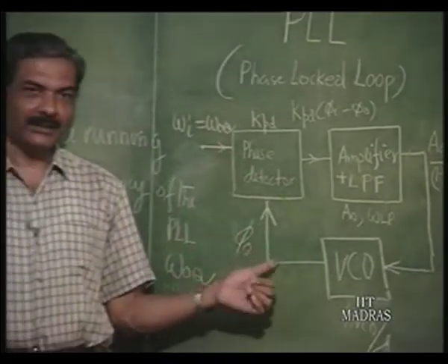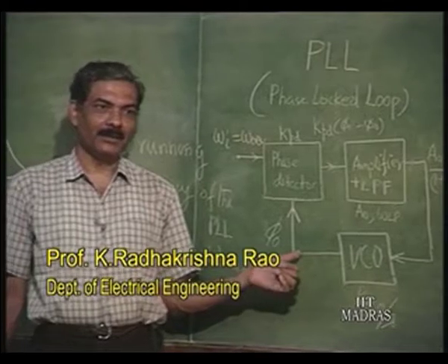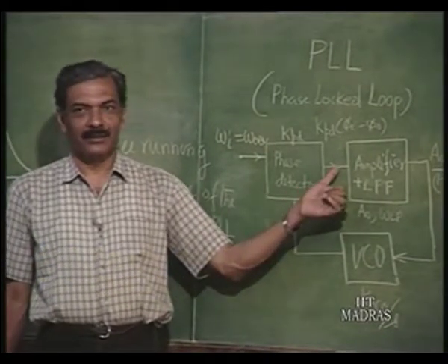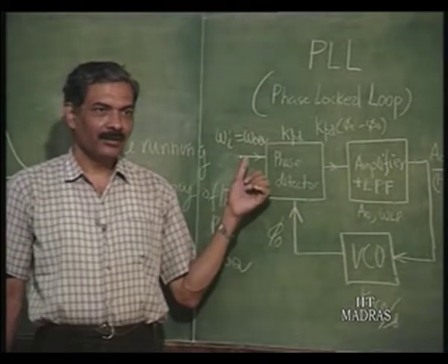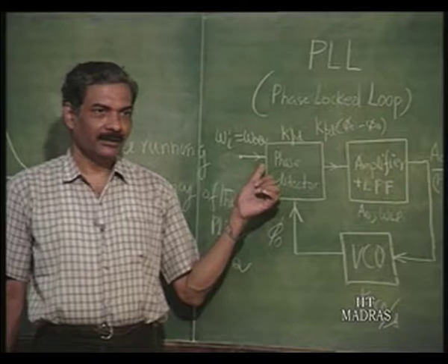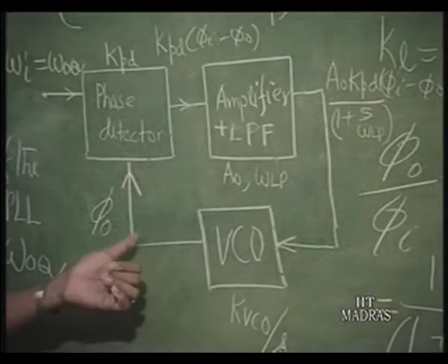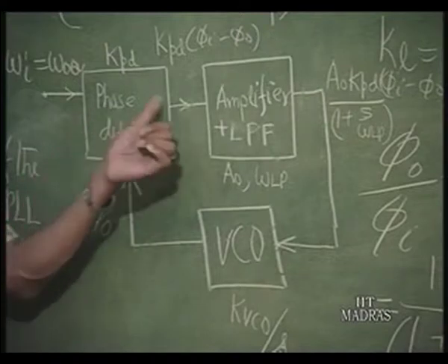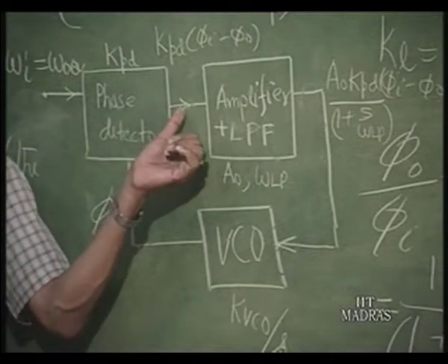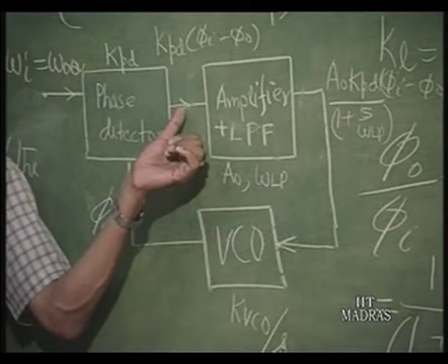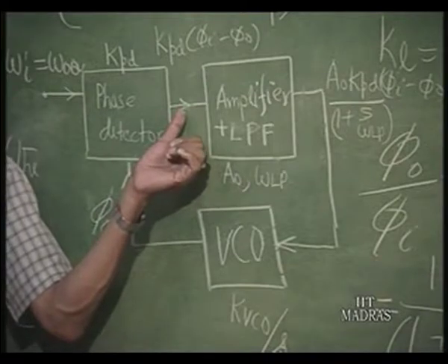That phase difference has to be equal to pi by 2 in order to have the average equal to 0, because in the multiplier it was Vp sin omega 1 t, Vp sin omega 2 t divided by 10, which means it is going to respond to omega 1 minus omega 2, which is in this case omega phi, because omega 1 is equal to omega 2, but there is a phase difference.